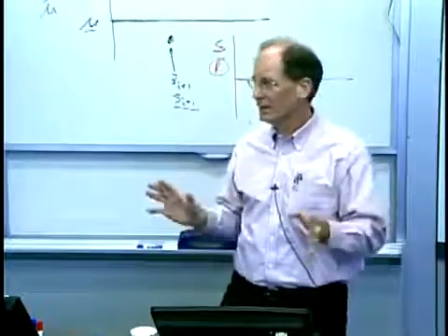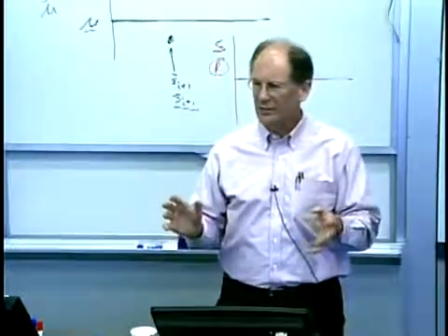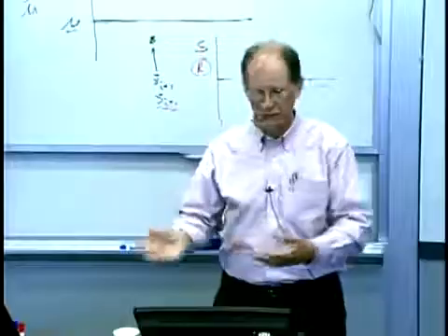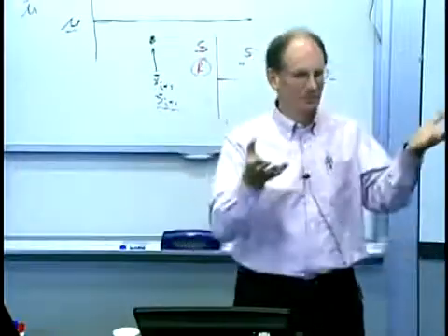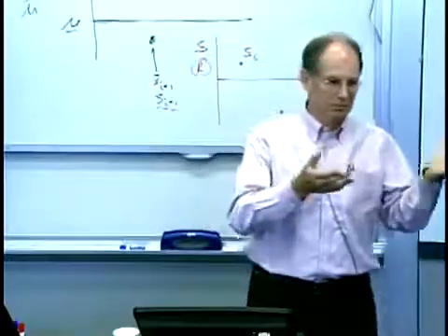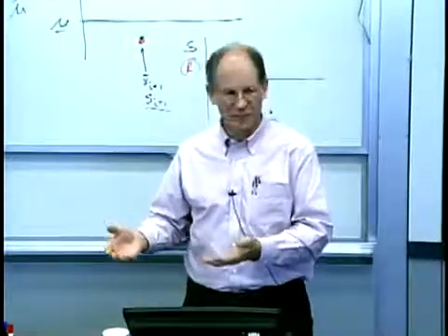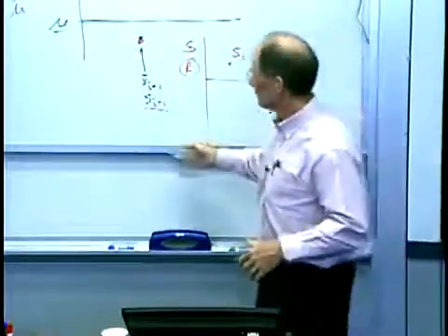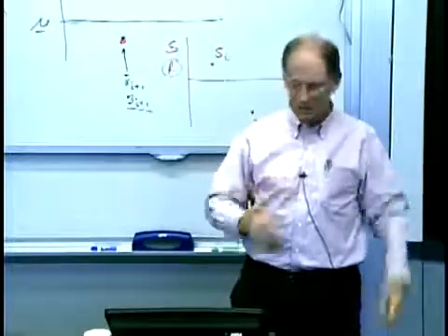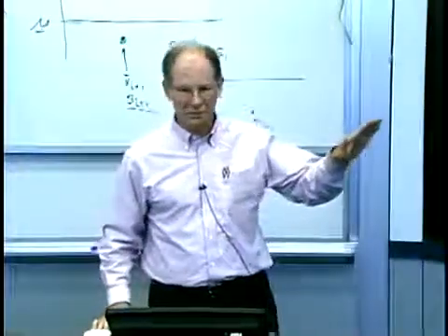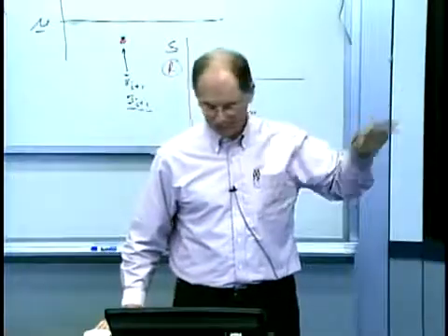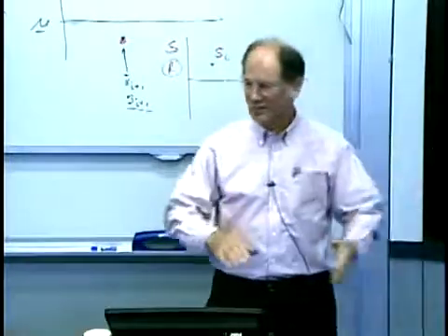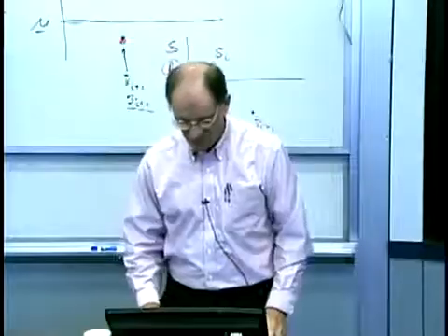Now, you're going to hear a lot about mean shift throughout the term because in some ways you can think of that as one of the most likely things to happen. You're making product with a certain batch of material and you change the batch. Something changes. You have a shift change. You have PM on the machine, preventive maintenance on the machine. And the next time you run it, things jump up. So the underlying behavior, something in this model just made a step change and you saw it out there. Linear trends, obviously, something like tool wear, something changing over time. Periodicity, it could be temperature changes, it could be something that's underlying, that sort of thing.